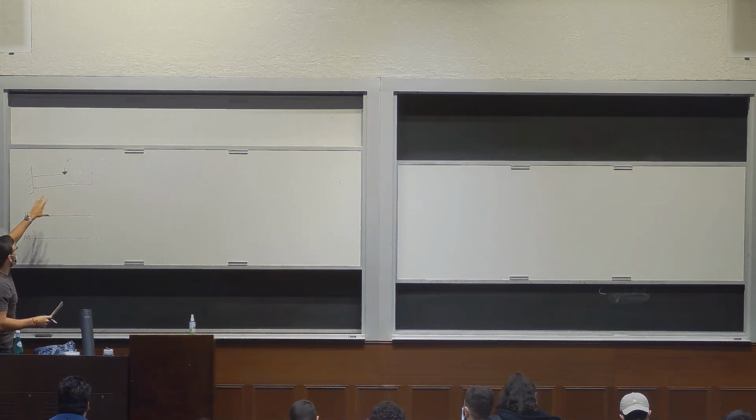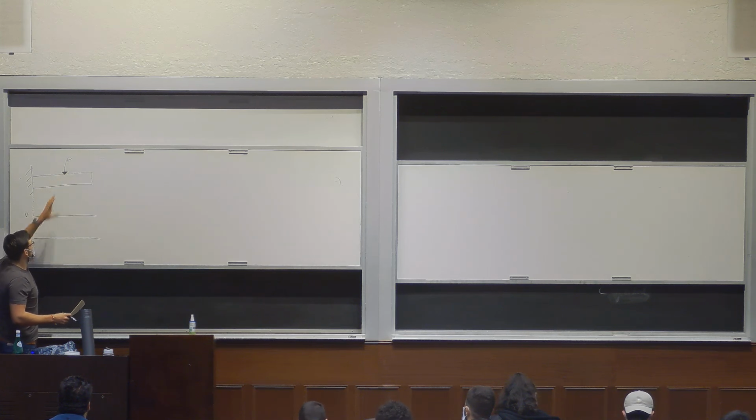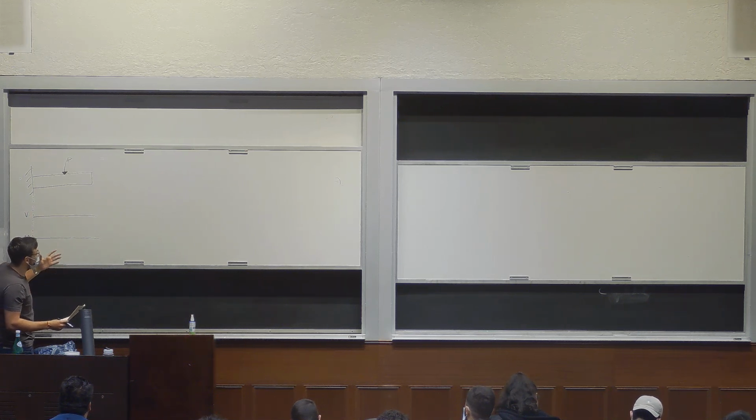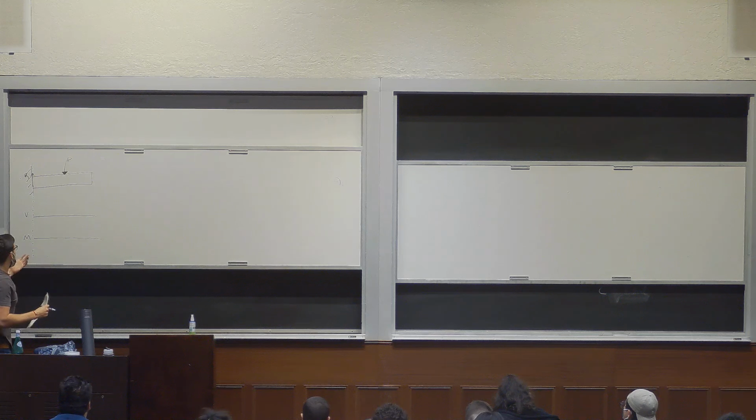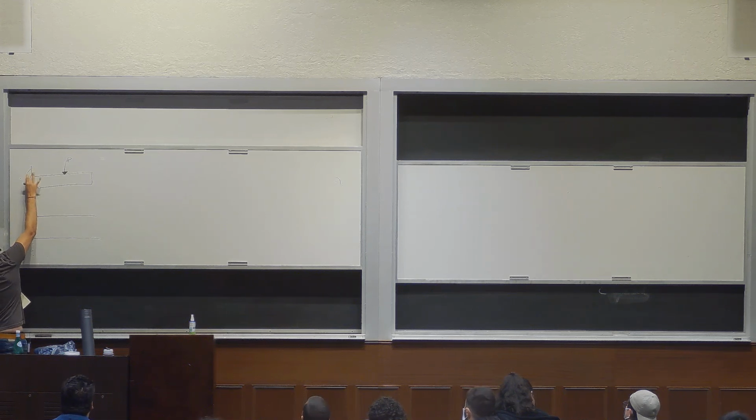If you have a force applied here, it has to be in equilibrium, right? So it has to be supported by the same amount of force in the y. The sum of the forces in the y direction has to be zero. So there's a reaction force here, R, and the magnitude has to be the same as the applied force. So it's going to be equivalent to P.